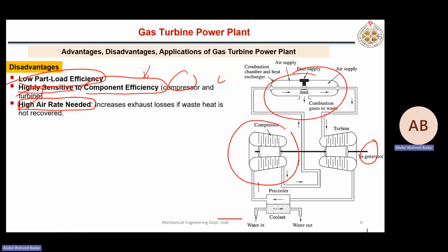But that will give us very high temperature, more than 2000. That's why we use excess air, so that this temperature should not go too high, 2000 plus. So that's why in gas power plant, we use extra air, excess air. Small amount of air is used for combustion. The other is not combusting. They are just decreasing the temperature to our desired level, which we need normally here around 1000 degrees Celsius. So here, the amount of air which is used in the combustion is much, much bigger.